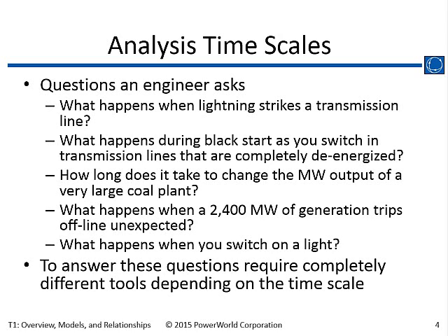And this is looking at time analysis of a power system. Some questions engineers might be asking are: what happens when lightning strikes a line, black start on a transmission line, changing the output of a coal plant, loss of a large generator? And the key transient stability fault we run is the double Palo Verde fault in the West, and I've run that a lot of times.